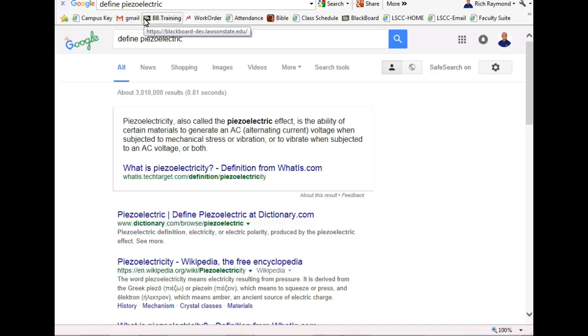Piezo is predominant right now in cigarette lighters. No, it's regular old butane or propane or whatever. Used to, you had a flint and a little wheel. You spun it around, hit the flint, and shot a spark out. Now you've got a little button that you push, and you hear a snap. What it's doing is popping against a piezoelectric crystal. That generates a voltage and causes it to arc.